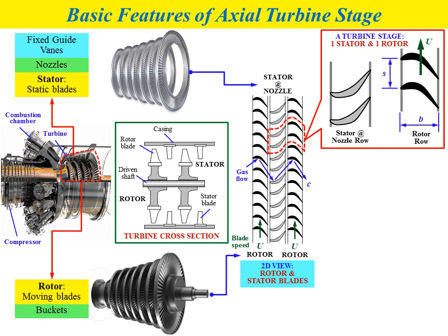Normally for turbine we will start with stator and then rotor blade. The figure shows parameters such as S, which represents the spacing distance of two identical blades, B represents the rotor thickness, and U is the blade speed. So we only have the U vector just for the rotor because the stator doesn't move, so we don't have U, which is referred to as blade speed, for the stator.